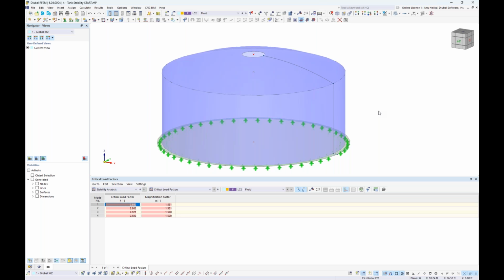And when we refer to the various codes, there are ways to consider these imperfections. And one of them is to outright directly model the imperfection in our FEA model. So I would like to show you now how we can directly model these imperfections and integrating it with the structure stability in that first buckling mode shape.